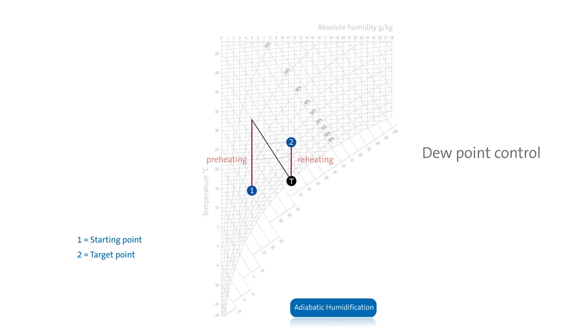As the HX diagram shows, the humidification process in this control method is performed in ranges with a very high level of relative humidity. However, the higher the relative humidity, the more difficult it is to carry out humidification. In addition, the dew point control system must be heated both before and after the humidification process. As a result, the air conditioning system requires 2 damper registers.